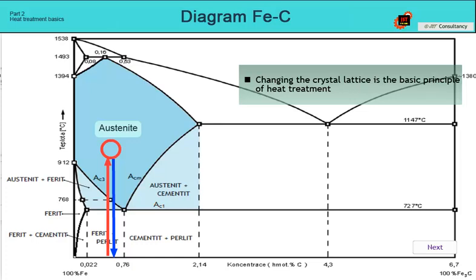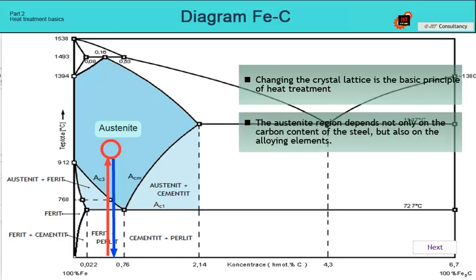One of the most important components of the phase states of iron is austenite. However, the austenite area is very diverse and depends significantly not only on the amount of carbon, but also on other alloying elements. Therefore, for each type of steel, depending on its chemical composition, the austenite region will vary slightly, just as the equilibrium phase diagrams of these different steels will also differ.